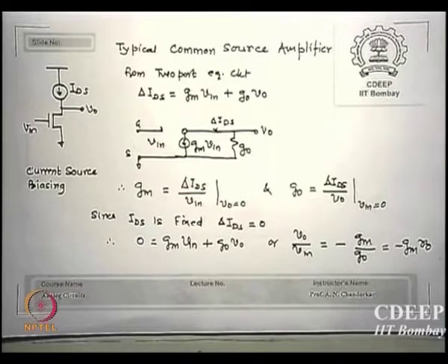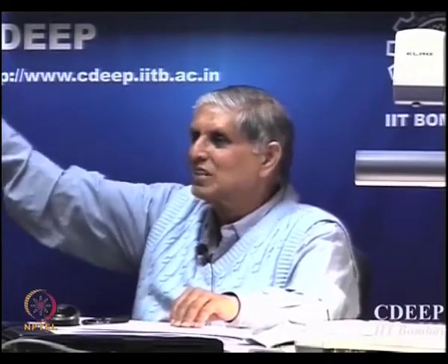What does V0 by Vin mean? The gain, AV, the voltage gain. So the voltage gain of a transistor when biased with a constant current source is, that's why I call it intrinsic, Gm times R0. Next time we'll start the actual MOSFET amplifiers. First we'll start with biasing, then we'll show you some amplifiers, and then we'll do bipolar. Why do we want to postpone bipolar? Because as I said, 60-70% is MOS, so let's do MOS first. Thank you for the day.